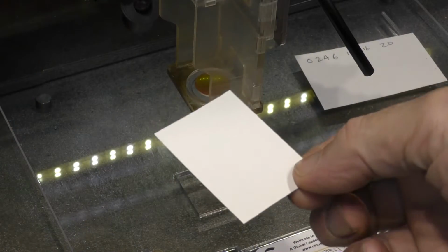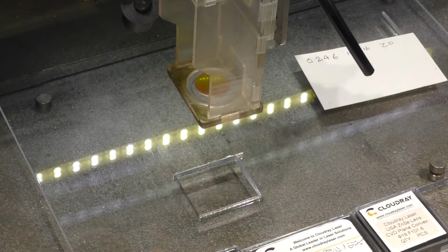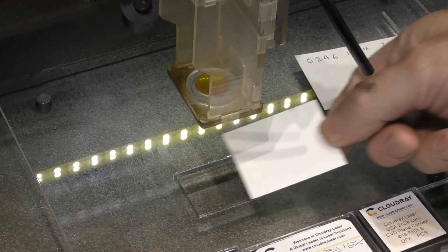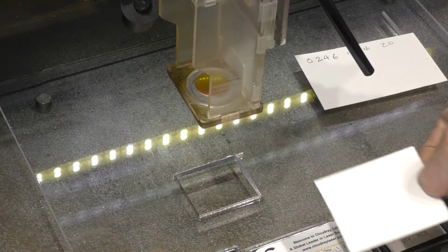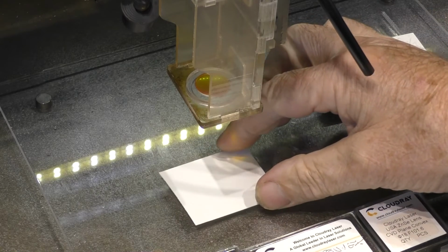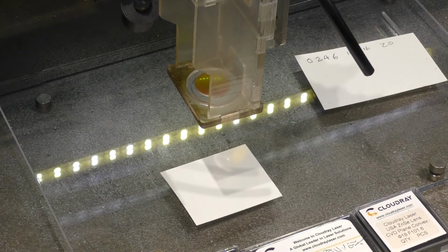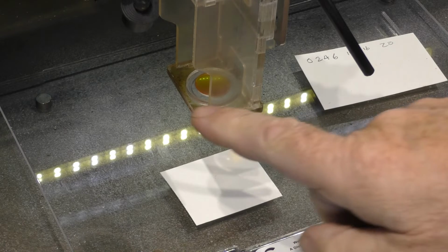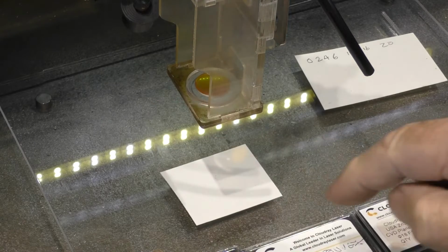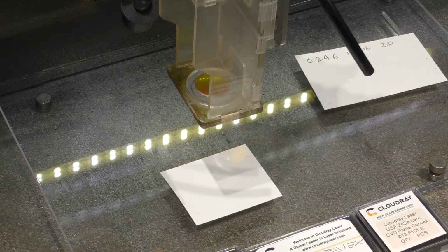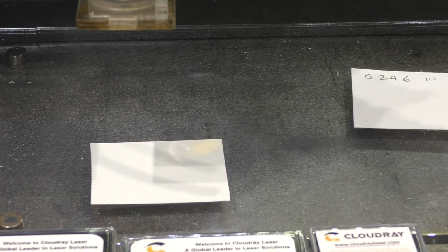19.993. So I have a small piece of my thin test card here, which is 0.3 of a millimeter thick, and it's a nice soft card, which is the standard card that I've used throughout these tests. It's thin, and I'll explain the reason for thin as well shortly. 2.5 inch meniscus PVD lens in here, set 20 millimeters below the focal point. So now I'm going to give this a 20 millisecond pulse of energy at 70%. Now 70% power on this machine is about 60 watts coming through the lens and hitting the material.